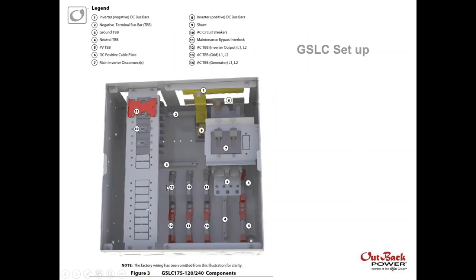This is the same busing system down here. This is the load center that you would use for this application. If you're doing a normal AC coupling application, this is a pre-populated load center, all pre-wired, with your relays and your remote operated circuit breakers here, and you just basically are landing your wires at that point.